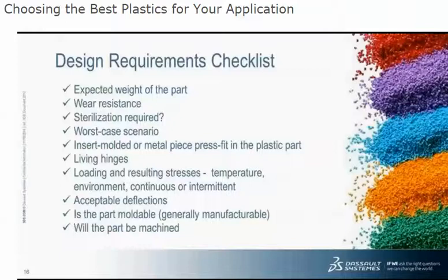I've seen applications where manufacturers will actually add a metal to the plastic just to make the part heavier, so it feels better in someone's hand when they pick it up. Something to think about. Will your parts have to be sterilized? Again, in medical devices, that's really important to consider, because some plastics can be sterilized using some techniques. Other plastics, you might have to sterilize using other techniques.